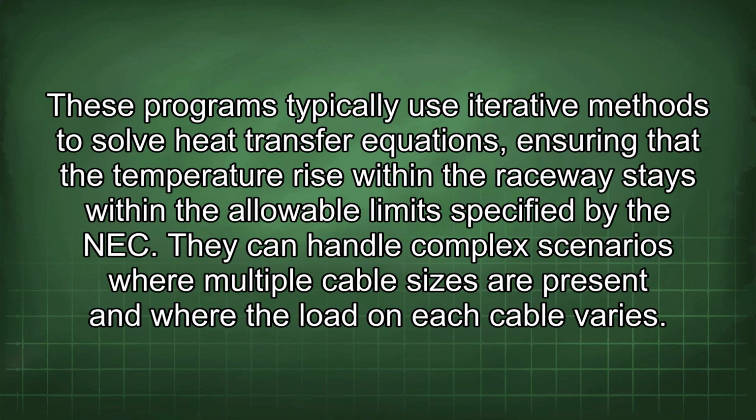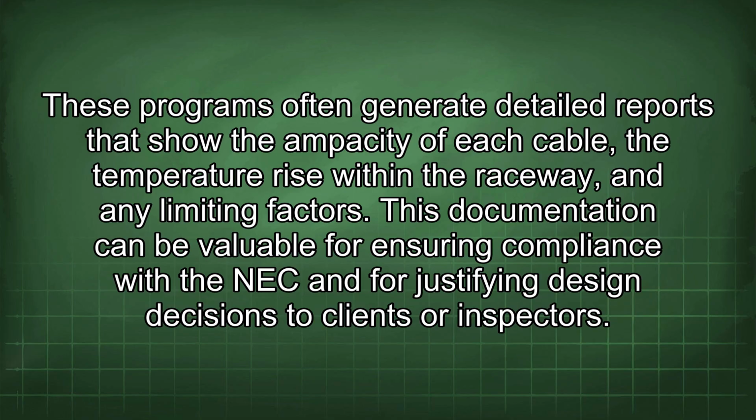These programs typically use iterative methods to solve heat transfer equations, ensuring that the temperature rise within the raceway stays within the allowable limit specified by the NEC. They can handle complex scenarios where multiple cable sizes are present and where the load on each cable varies. These programs often generate detailed reports that show the ampacity of each cable, the temperature rise within the raceway, and any limiting factors.